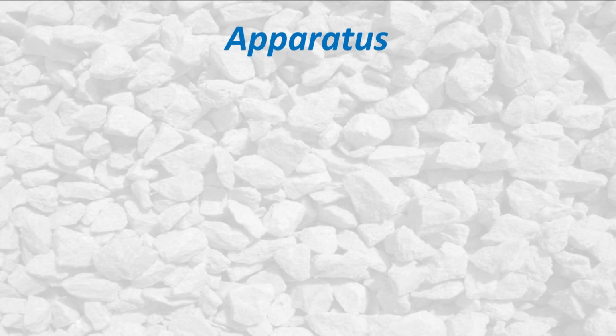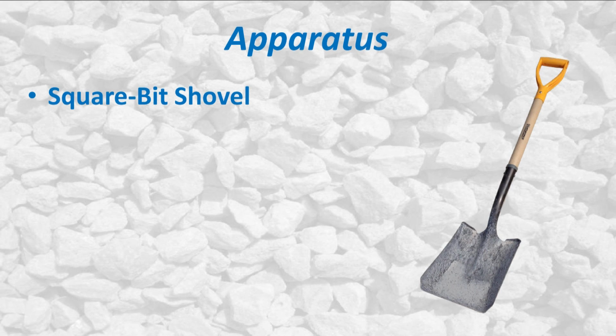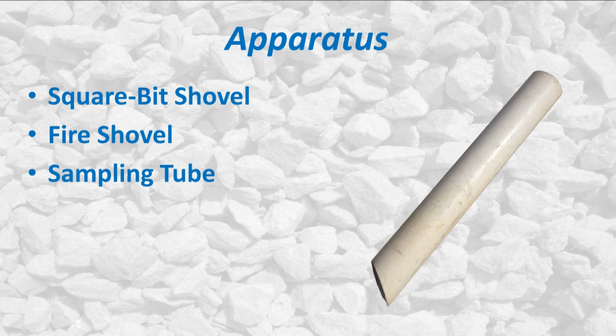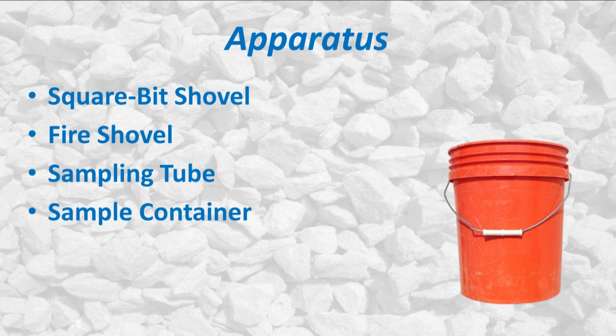You will need the following items for this test procedure: square bit shovel, appropriate size; fire shovel; sampling tube, 3-inch (75mm) minimum diameter and 3 feet (1 meter) minimum length; and a sample container.